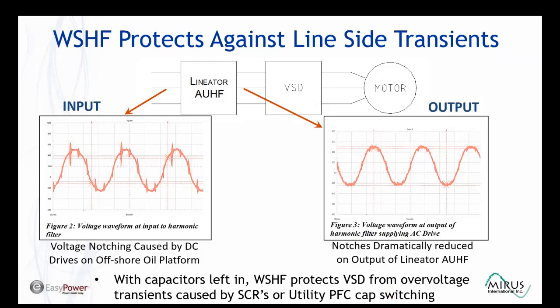We also had applications where the over voltage transient was introduced by the utility's power factor correction capacitors. When they switch in their power factor correction capacitors, it causes a dip in the voltage, there's an overshoot and ringing, and the input filter can protect the drive in those cases as well. But if that is the need, then you need to make sure that the capacitors are kept in the circuit under no load conditions.